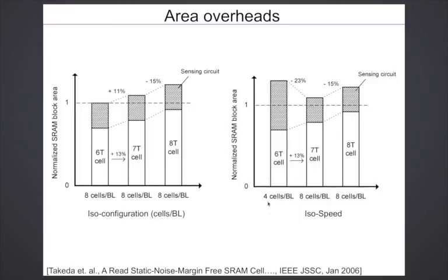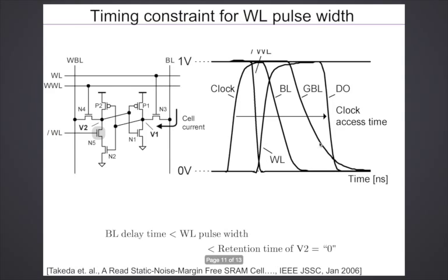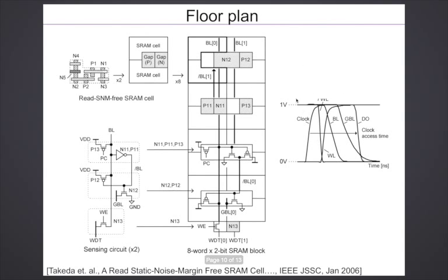So whereas if you see currently the memories and macros which you use, you don't do such heavy partitioning. You will have 64, 128 cells and so on. And that is where one of the problems comes with this sub-threshold SRAM design, where you are really pulling the voltage down. You are doing this heavy partitioning. There is a reason for doing this heavy partitioning, and that is basically if you go back out here,